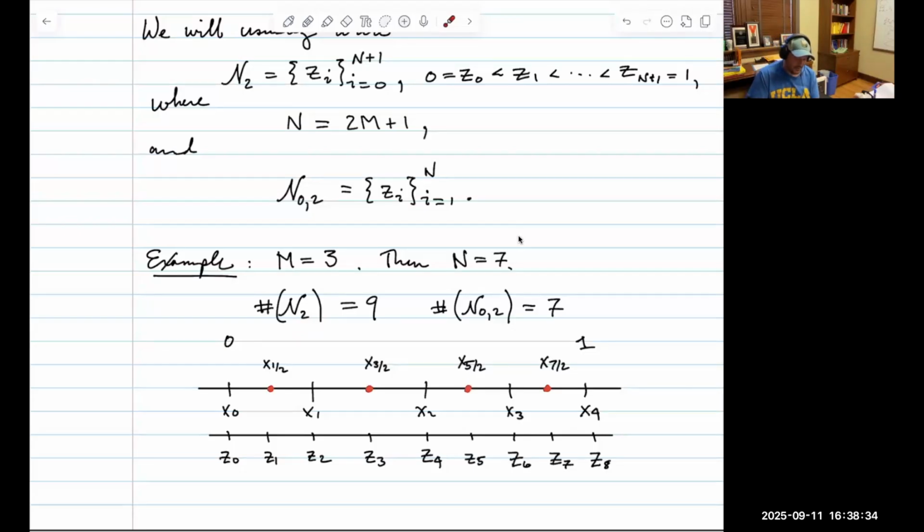I'm going to call those z points, and the z points are what I call nodal points. They're always called nodes. I'm going to differentiate in my finite element language again and again: nodes are always vertices of triangles plus midpoints of edges, and maybe some other points as well. But the nodes are where things are happening. The partition itself just has vertices, but my nodes have more points in them.